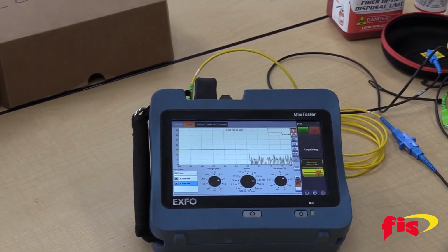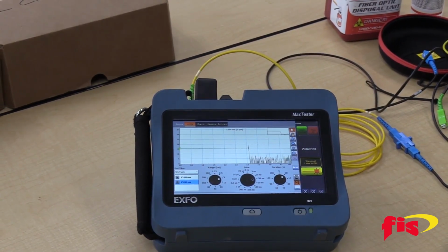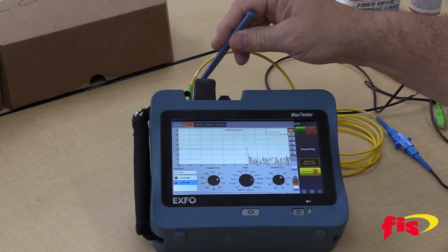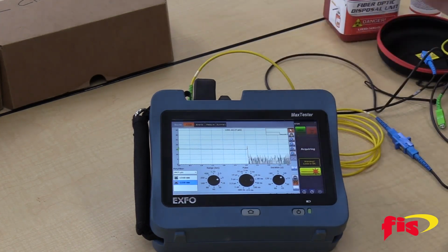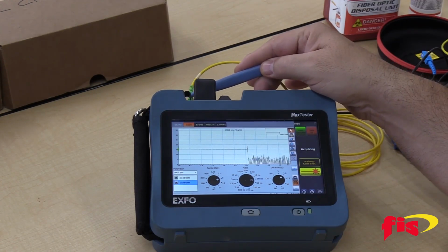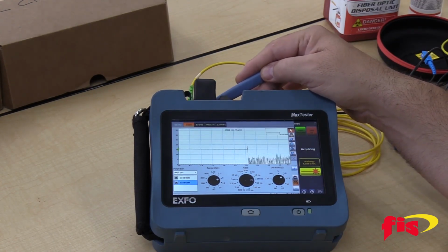The other reason is connectors wear out. The connectors on these pulse boxes and launch cables will wear out. They'll have to be repaired. Connectors will wear out in your OTDR. So there's the other hidden advantage of using a launch cable: if I'm testing a lot of fiber and I don't use a launch cable, I'm plugging into my OTDR could be hundreds of times that day, and that's going to shorten the life of that connection.